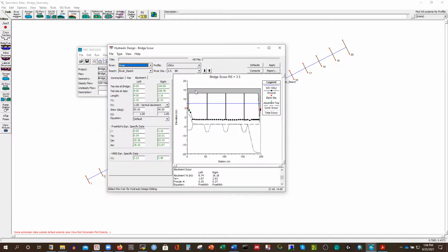I already demonstrated how to generate a model for non-uniform flow. It is because of the boundary condition. If you import a time series of flow rate that changes with respect to time, then it is going to be an unsteady flow, because time is the main criterion for determining whether a flow is steady or unsteady.